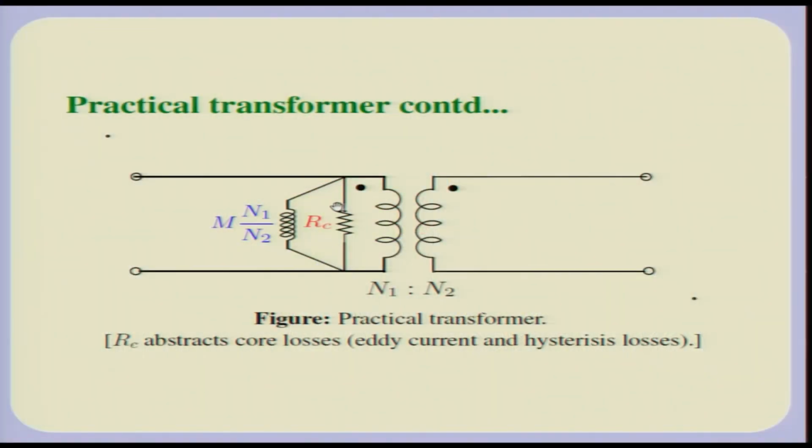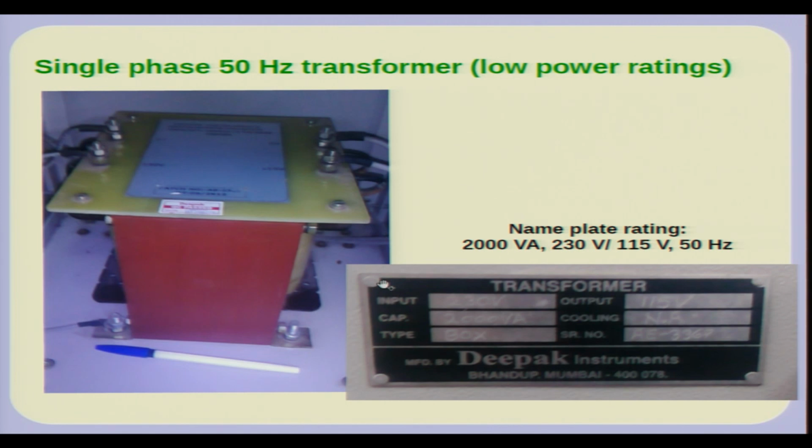So, the apparent power magnitude on both the primary and secondary coils is the same, assuming that the open circuit current, which is also called the magnetizing current, is low. Okay. If you assume that the magnetizing current and eddy current effects, that is the current drawn by these shunt branches here, are very low, then the apparent power on the primary and the secondary side is equal. Okay.